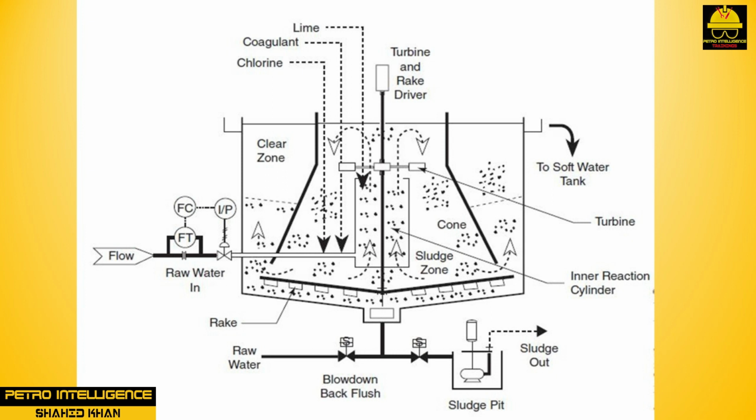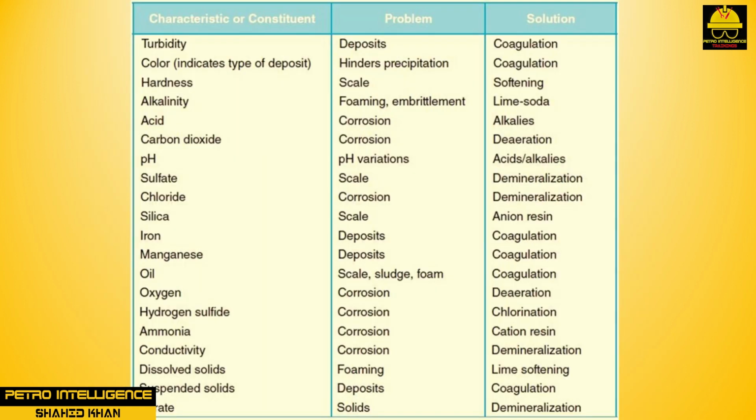Blowdown depends upon the amount of suspended solids the boiler can handle. It is not unusual for blowdown to equal 5% to 10% of the total capacity. Blowdown is controlled through an instrument designed to measure the electric conductivity of the water. Blowdown ports are typically located on the bottom of the boiler so accumulated sludge can be removed. This table lists common boiler water problems.